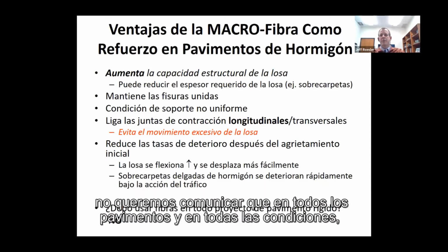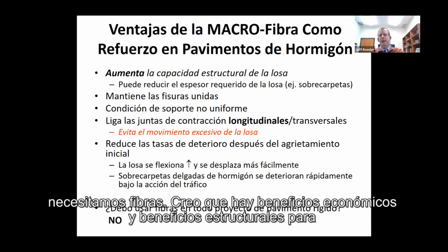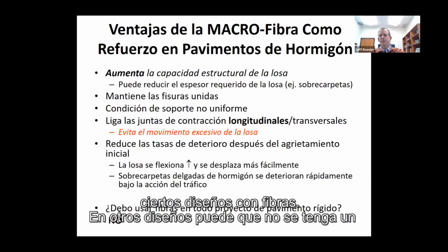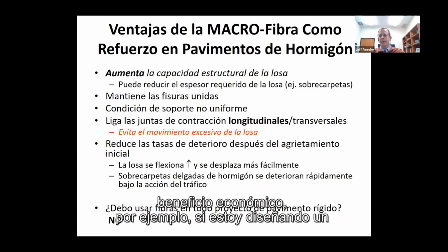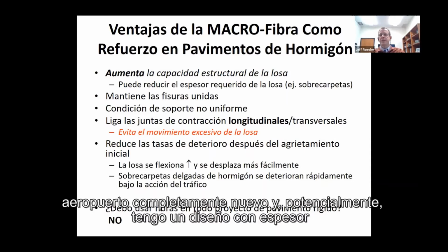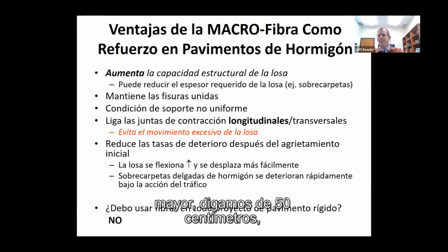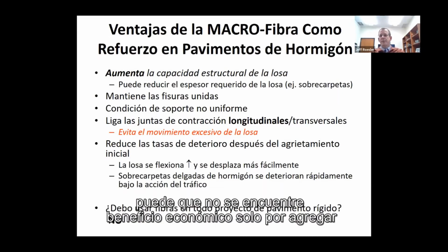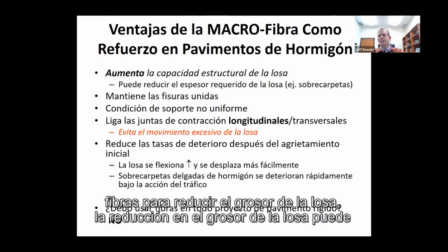Having said all that, we don't want to communicate that all pavements and all conditions need fibers. I think there are economical and structural benefits for certain designs with fibers. In other designs, there might not be that economical benefit. For example, if I'm designing a brand new airport and I have a thick design, let's say 50 centimeters, I may not find it beneficial economically to add fibers to reduce the slab thickness.